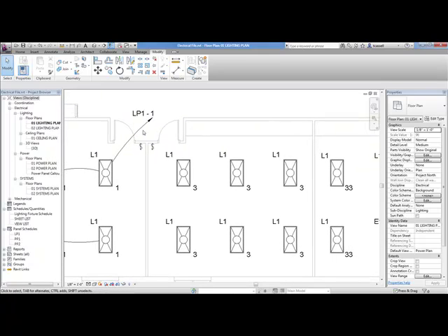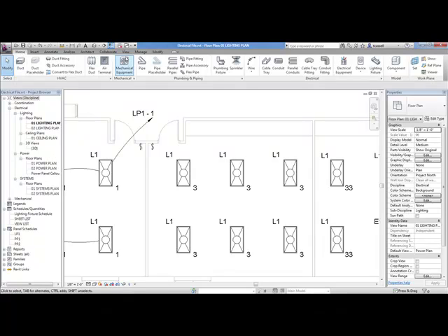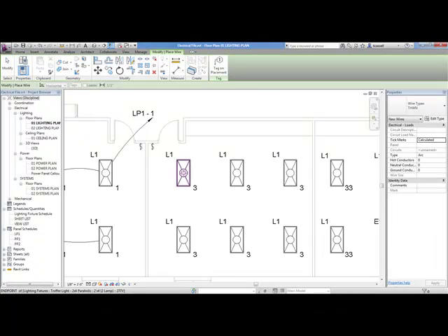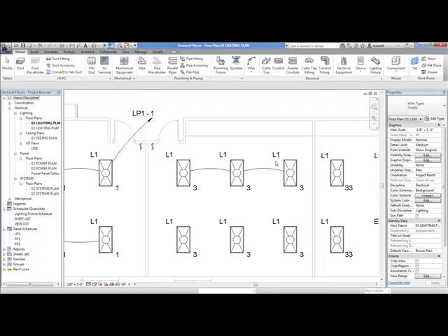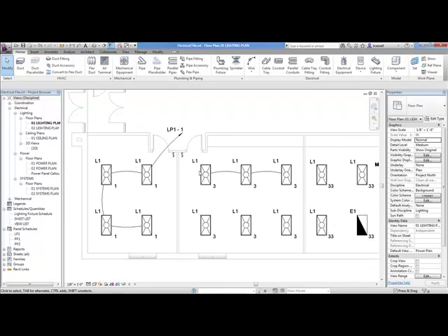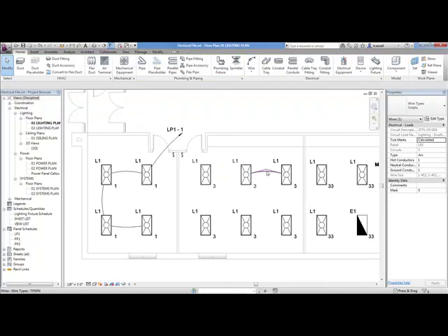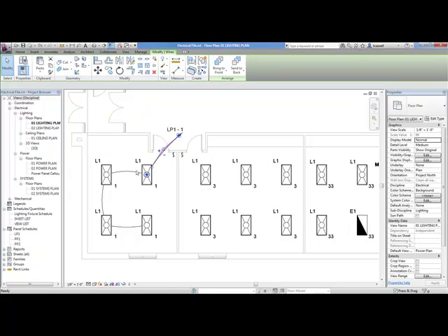If you were to connect a multi-branch circuit, it will show you an arrowhead for each multi-branch that you have, and you can draw as many wires as you want or none at all. Again, doesn't really matter at all if you show or use wires. It's completely optional, and I know that a lot of electrical engineers at this point do not show wiring at all.